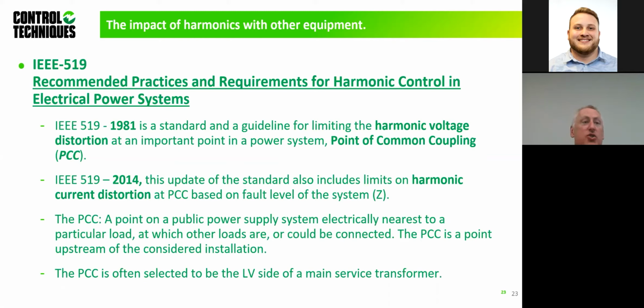And of course, that makes sure that the vendor, if you don't know what your supply capacity is, ensures his current is down to a minimum to make sure that the resultant voltage distortion is kept down at the same point. So we talk about that. Current distortion is very, very critical. If you have a 519 challenge with current distortion, usually we have to adopt a different method of harmonic reduction, and we'll talk about that a bit later.